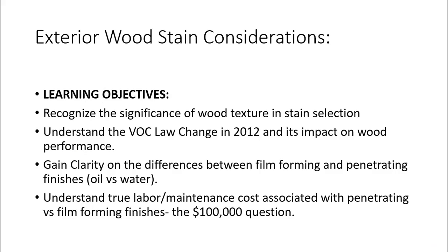So I did this in order of importance, even though the top two are 50-50. The significance of wood texture in stain selection is that it's the most important determiner of the lifespan of your stain. The VOC law change in 2012 was a game changer. In 2012, they changed the law that said how much oil you could put in a stain. Basically, you can take everything you thought you knew about stain before 2012 and tear it up and throw it out the window. As of this recording in 2019, we have about a 7-year window to measure the performance